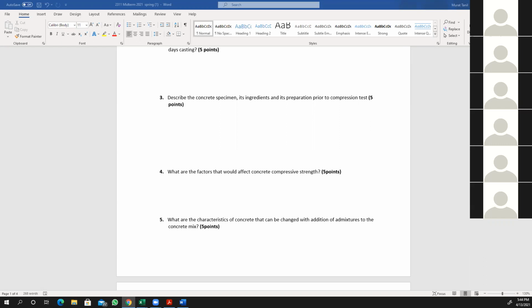So we're looking at question number 4. What are the factors that will affect the concrete compressive strength, which we discussed a few minutes ago? Just like the quality of ingredients, the ratios used, cure time, temperature, internal air. Perfect. That's enough. Thank you so much.